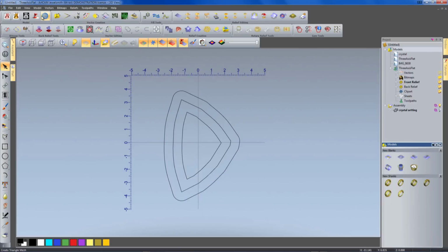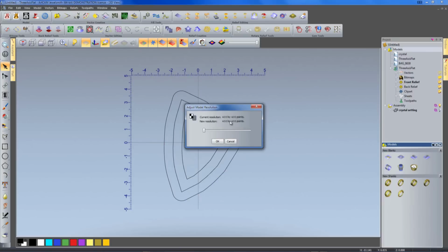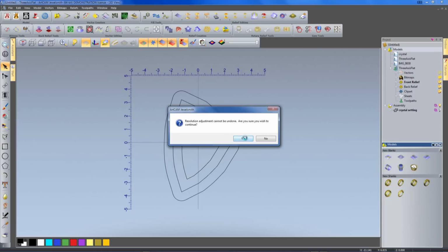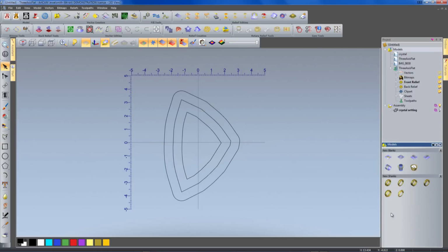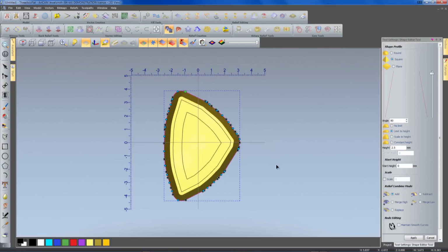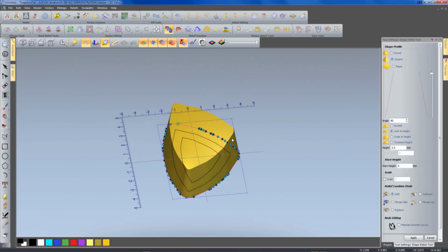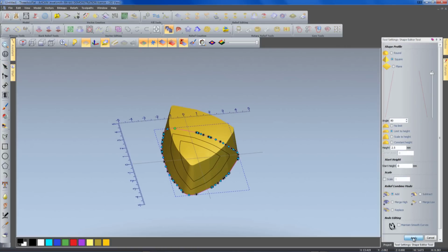Talking about making a higher resolution, you can go into here and set the resolution size, model resolution. You can see it's set at 400 here. I can say 1000 by 1000 even at 10mm, which gives me even finer detail on the settings if you really want to. So again, I'm just going to select the F12 button. That's already selected, already knows what I want to do. That'll be okay. And I'm going to select the next vector again.